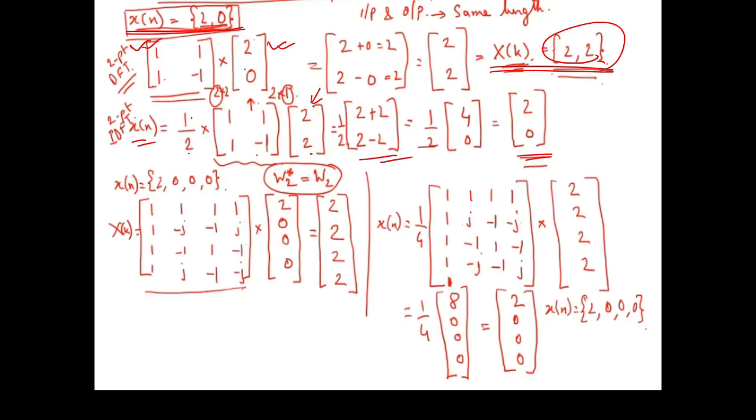Now, if you see, DFT is performed for 2-point, 4-point, 6-point, 8-point, all the even numbers. Since basically x of n, what I have given, x of n I have given as 2, so to make it even, we have to pad the signal with 0 to make it a 2-point compatible signal for 2-point DFT.